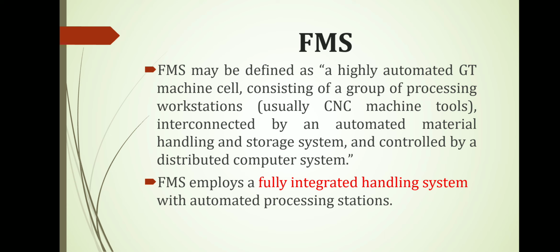FMS may be defined as a highly automated group technology machine cell consisting of a group of processing workstations. Mostly we utilize CNC machine tools interconnected by an automated material handling and storage system and controlled by a distributed computer system. FMS employs a fully integrated handling system with automated processing stations.